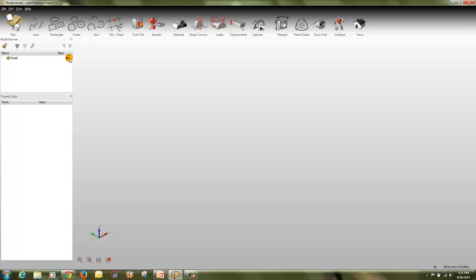The push pull faces tool is used to push or pull flat or cylindrical faces created with the sketching tools. It can be used to extrude solid from faces, create and resize holes, modify or eliminate rounds, and modify wall thickness. This tool is useful for defeaturing a part to make it suitable as a design space for optimization. Pushing and pulling without snap: as you push or pull a face, a ruler appears showing how far the face has been pushed or pulled.